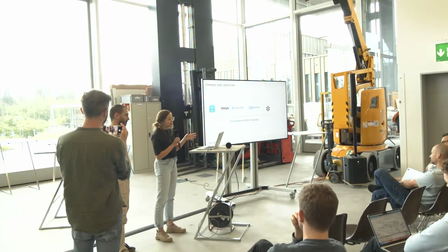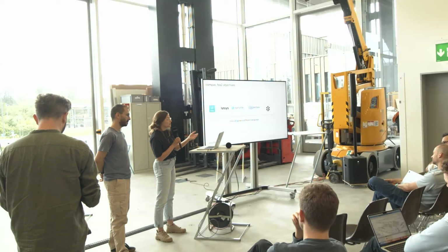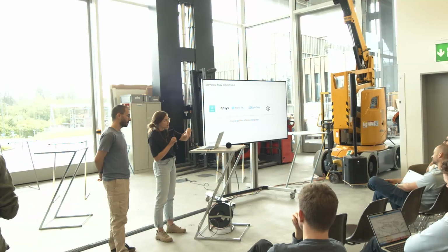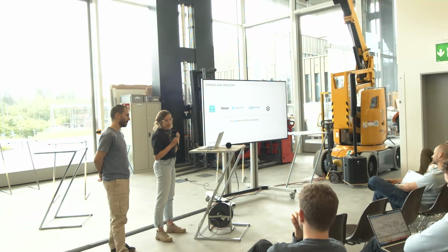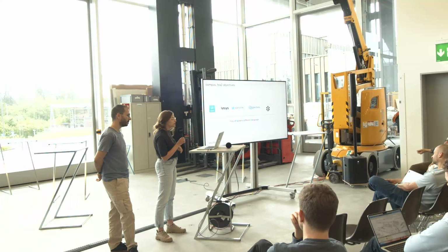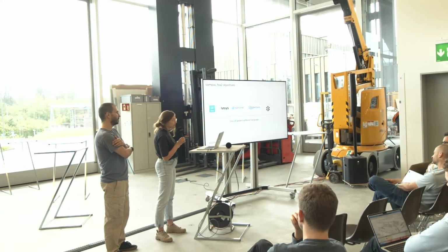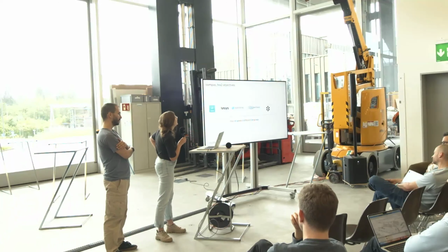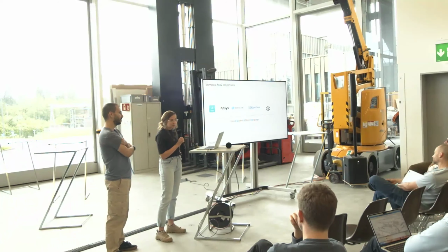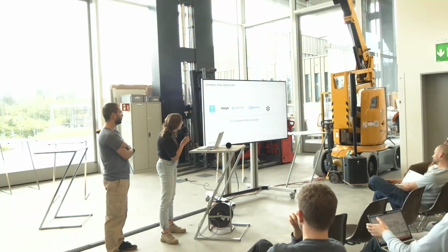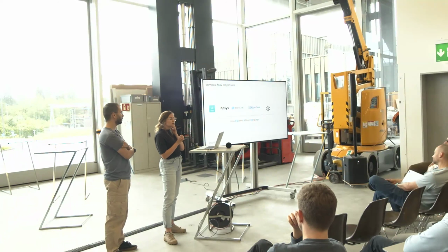So to make it easier, I discretize this object in nodes that are linked with elements. So I can make the study possible, then I study it and I can get my results for structural assessment. To do that, I have several software that can do finite element analysis, such as Abaqus, SOFiSTiK, or OpenSees.